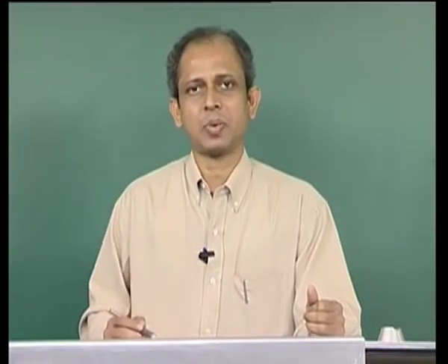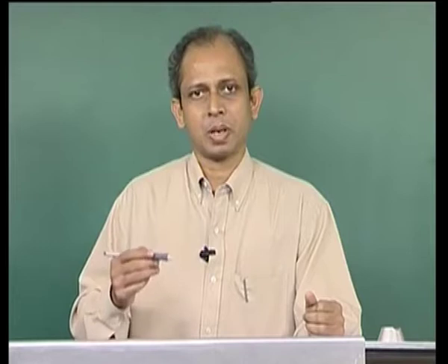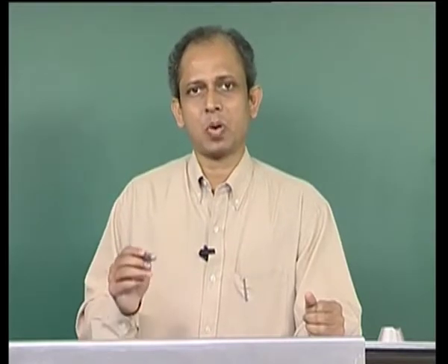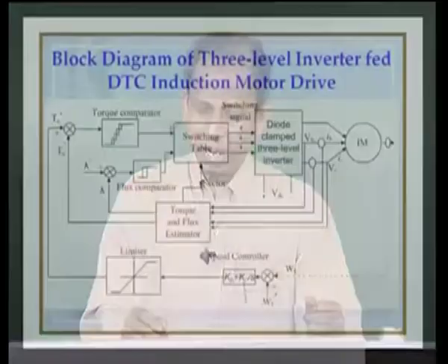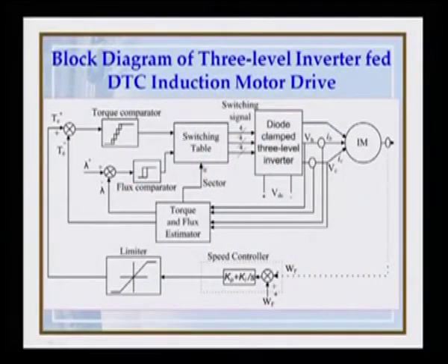The sector information will help us apply the appropriate voltage vector to the induction motor. So, this is what we have here, and the output of this is the voltage vector, and when we know the voltage vector, we can find out the switching signals.